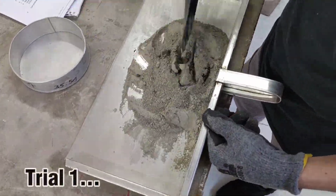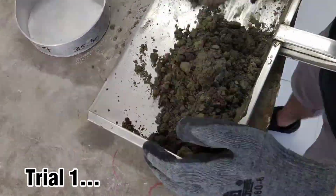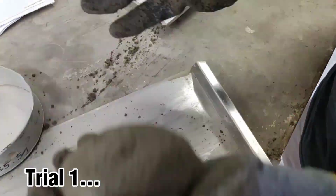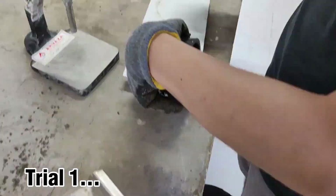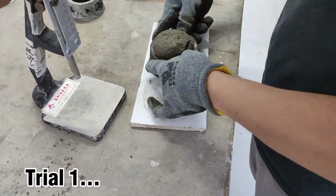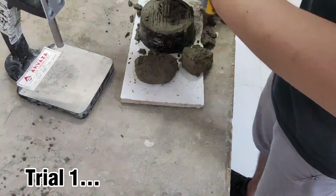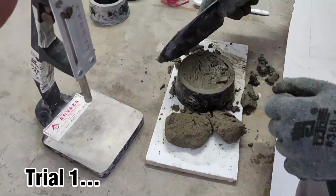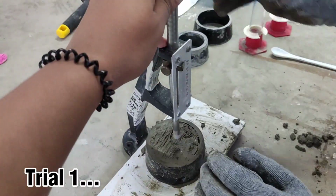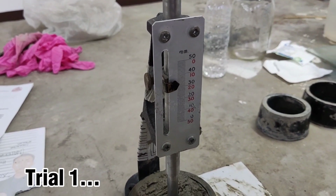For the first sample, we added 30% of water, which is about 250 milliliters, and followed the procedure. This sample resulted in a Vicat penetration of about 35 millimeters from the bottom of the mold, which is way above the required depth for a normal consistency.